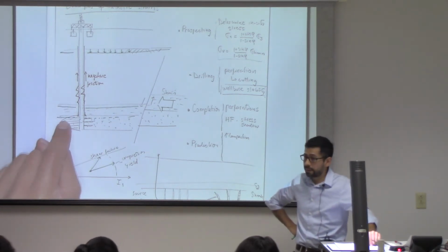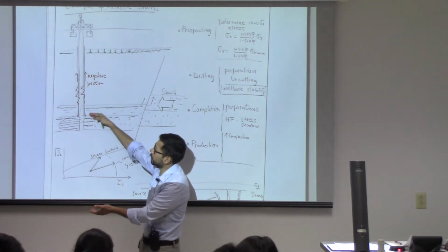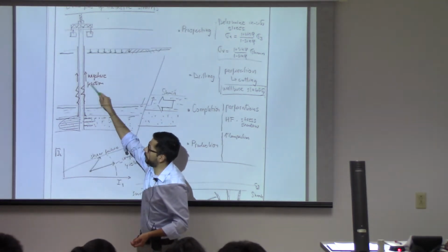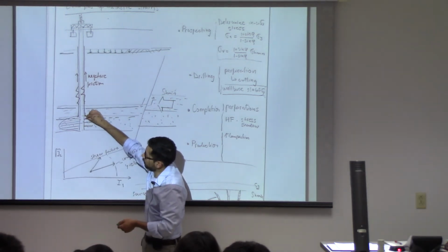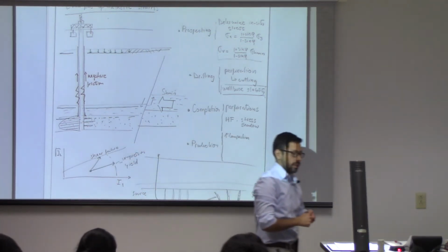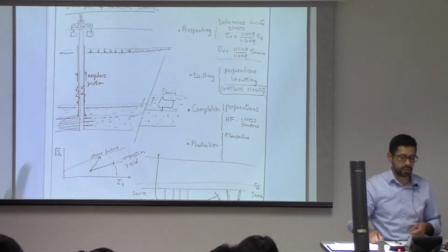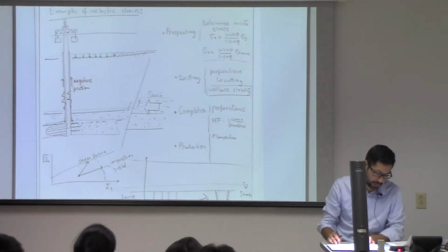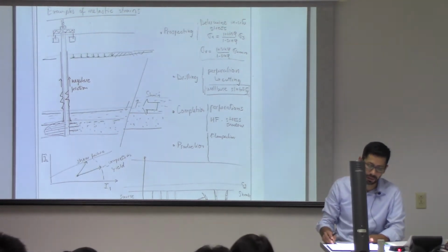But sometimes they have this problem of production, a lot of compaction, and the casing experiencing compression here on the top, and in this region, imagine if this section goes down, you can also expect tensile failure. So you can fail your casing if you have a lot of compaction, in addition to some problems that you may have at the surface because of settlement of the surface or subsidence, right? So compaction, subsidence, all of that.